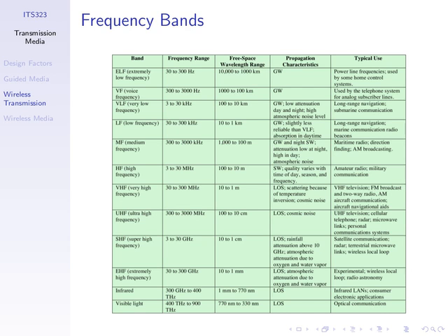So, when choosing a wireless system, you need to consider the frequency it uses. But the other thing is what application you want to use it for, what distance do you want to communicate? If you did the homework, you would use the free space path loss model and did a calculation of how far you can communicate. Remember, the distance is related to the frequency, or the path loss is related to the frequency.